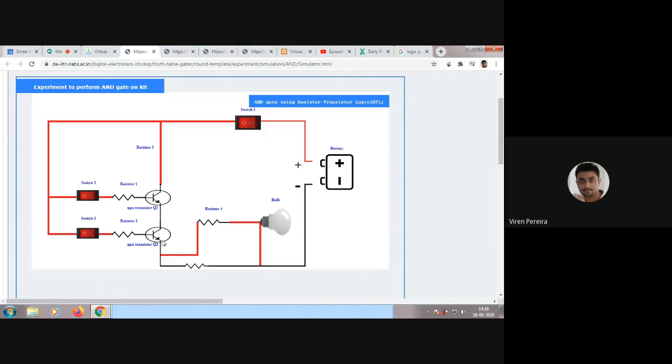Here also we have a transistor, normal transistor switching, NPN BJT. So when a base signal is given here, what happens? These two become short. Otherwise, if the base signal is not there, it is basically open. So it is a switch. Basically, if you give voltage here, this turns on. If you don't give voltage here, this doesn't turn on.